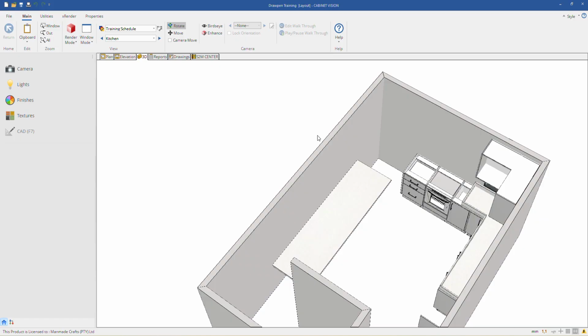So if I add the walls on, I put the ceiling, it should be fine. You can do that quickly. Just cover it, close it with walls, and then just add the ceiling. If that snapping grid is giving you issues, you can switch it off here on the bar. Okay. No, switch that one. Switch down. Then your snap grid is gone. Then it won't snap so weird on those little balls.